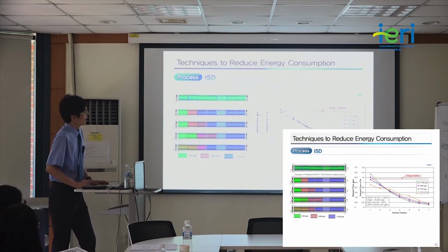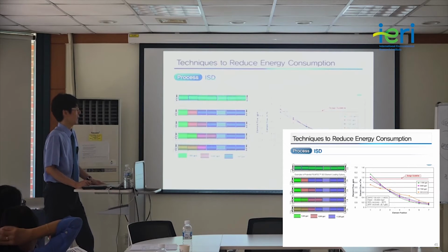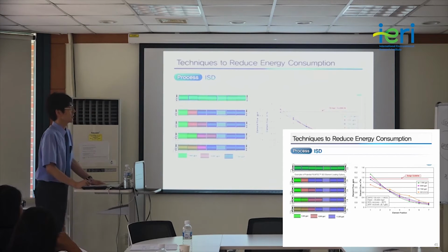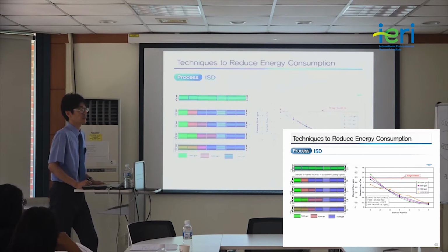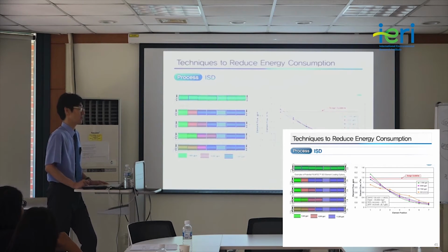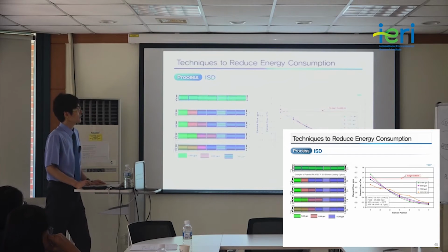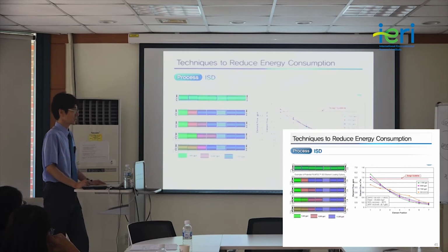The reason is, in the previous lecture, I mentioned that if there's a significant difference between the water flow rate in the inlet and in the outlet, in such cases, irreversible energy loss happens, so that the specific energy consumption increases. And so the solution is, if we can have the same flow rate throughout this membrane vessel, in such cases, we can reduce the irreversible energy loss.